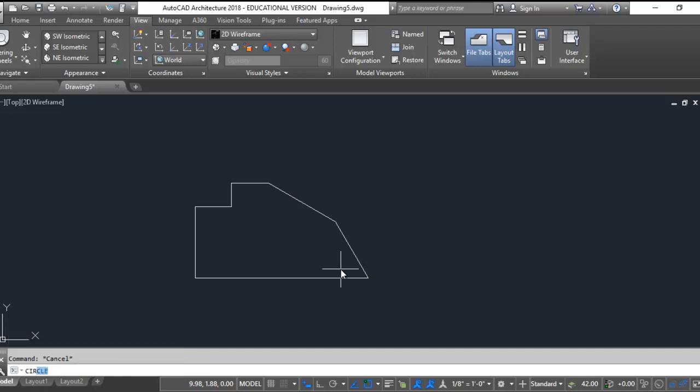Now I'm going to draw a circle. Just put it on this lower corner to start. D for diameter, 0.75. Move that circle, hit F8, so I'm moving directly to the right, 1.5, and I'll move it straight up, 1. And your textbook does give you a shortcut to move or create objects at a certain coordinate, but I find it more intuitive just to move a set distance like I'm showing you here.